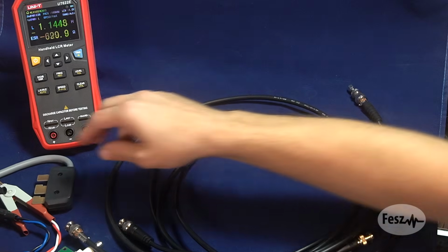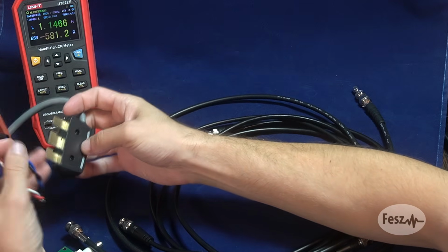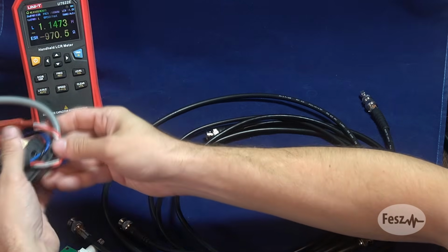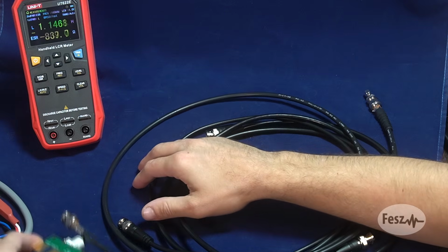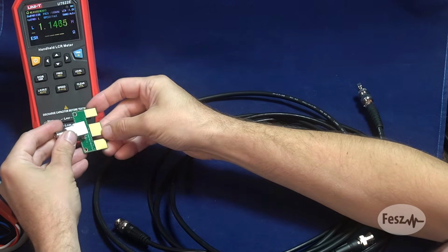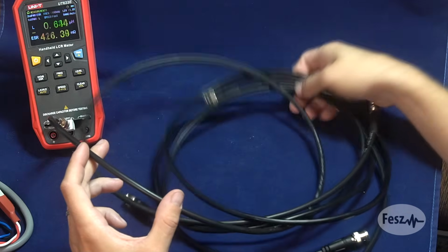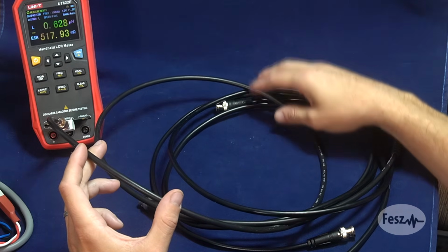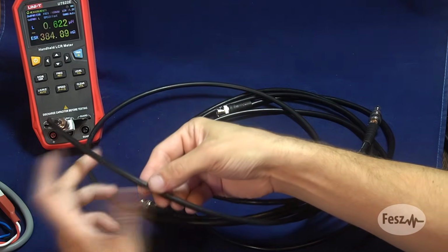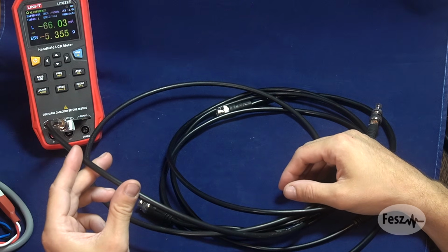To actually perform this measurement, I noticed that while the test leads that a generic RLC meter comes with are good enough for the capacitance measurement, when it comes to small values of inductance, these are quite inadequate. So I made a small adapter board with a BNC connector, and after calibration, I insert the test cable into this. For today's tests, I have 3 cables, which in theory at least are 50, 75, and 93 ohm cables, but we'll see based on our measurements what these really are.